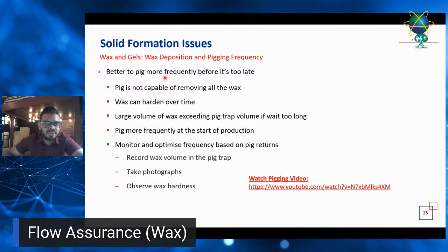So better to pig more frequently before it's too late, because if you delay your pigging, your wax tends to get hard. It will harden over time, so it will age. So if you pig too late, then your pig is not able to remove all the wax, and a large volume of wax exceeding the pig trap volume if you wait too long.